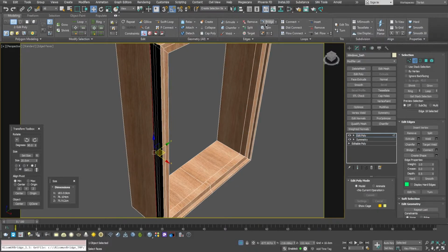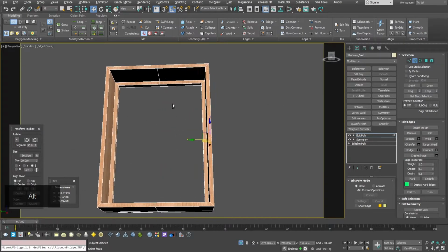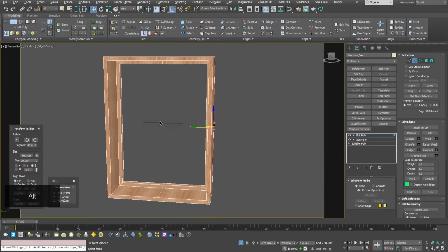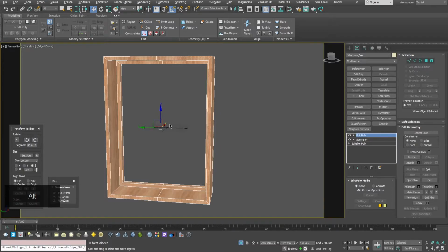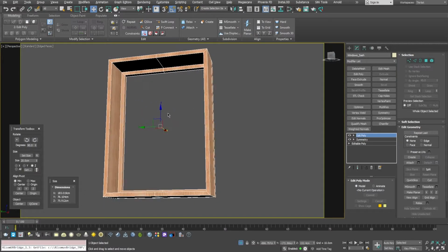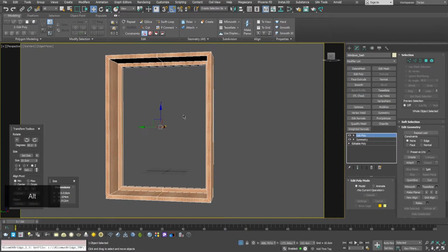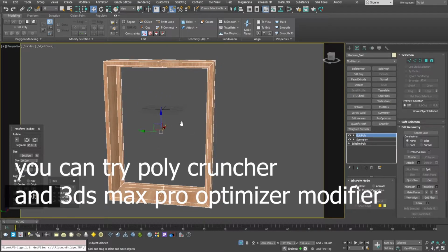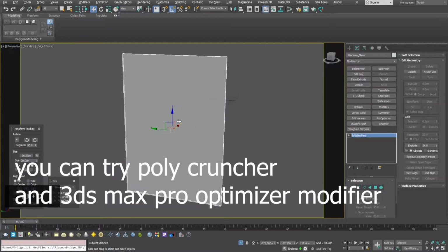And just try to bridge this again, and this is okay. But we still have bad geometry, and it's personal preference whether you want to use the Revit model, or build up your model in 3ds Max. I think the better way to approach would be to find some sort of cleanup tools, or something like InstaLOD. They can help a lot with the rebuilding of the meshes, so you don't have to do the manual processing.